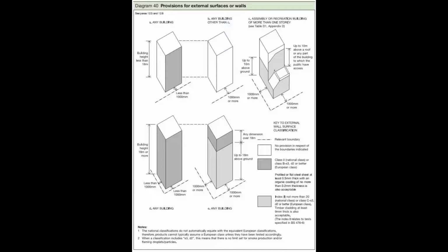That process with the approved inspector has to happen before the project gets to the point where you're retrospectively doing anything. So you can't have done the works, or you can't have commenced the works to a point where the local authority would automatically be appointed. That's quite a complicated scenario, but it's very orthodox. And in typical situations, large projects, an approved inspector would be appointed to work with the design team to develop a design that's in accordance with the regulations.